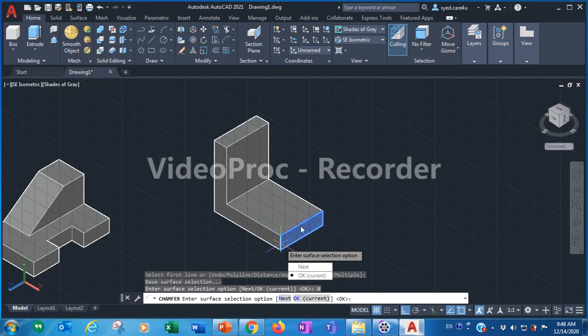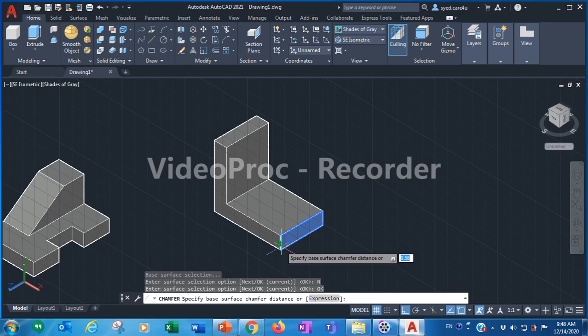And now see, if this is the surface you want to chamfer, if your answer is yes, okay, yes, you want to chamfer here and here, then press OK current. Now what is the base chamfer distance? Read here. What is he asking? Specify base surface chamfer distance. So the chamfer distance is 12. Yani, the first chamfer distance is 12. Type 12, then press enter.